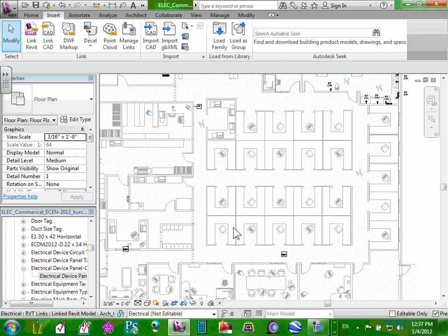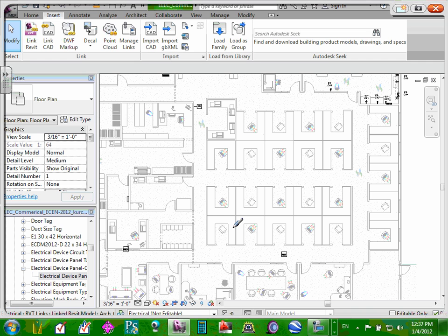Let me show you how to do that. Are you guys with me? What I want to do is put one J box here, and one J box here, and one here, and one here. These are J boxes with power, and each one of them will feed 5 cubicles. This one will feed these, and each one will feed these 5. Does that make sense? In this area, that's what I'm going to do.